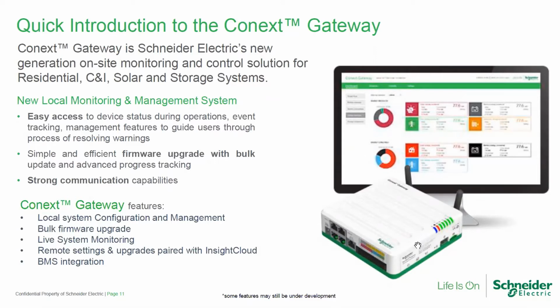The gateway has a number of other interesting functions. It not only allows us to monitor, it allows us to fully program the equipment, to change all the parameters and settings, to update the firmware or software of the equipment, and to do battery management systems control through a proprietary battery management system communication protocol, which Schneider has made available to all the battery suppliers. This is all done through the supplementary ports, CAN and RS-485, which can be seen there on that multi-plug, that 24-pin multi-plug connector.